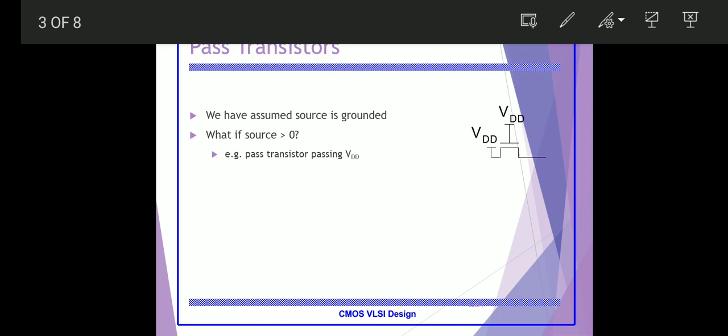It shows the implementation of the AND function using only NMOS pass transistors. In this gate, if the B input is high, the left NMOS is turned on and copies input A to the output F. When B is low, the right NMOS pass transistor is turned on and passes a 0 to the output. So this satisfies the truth table reproduced here.